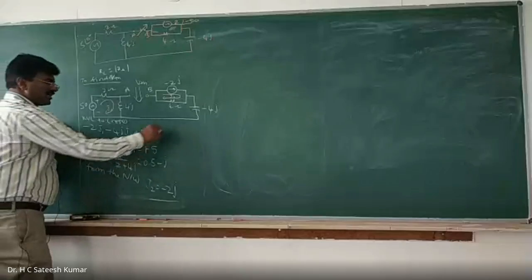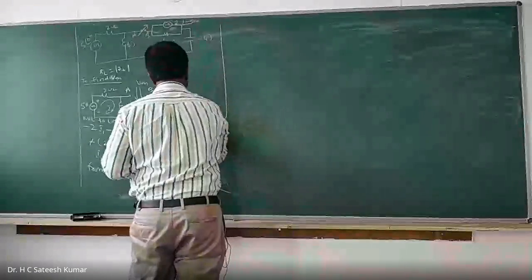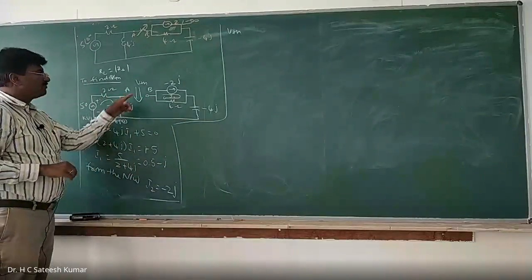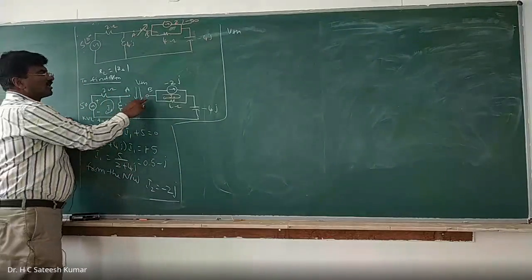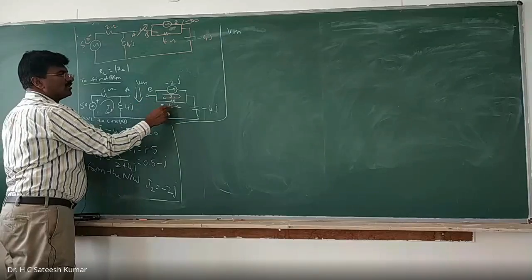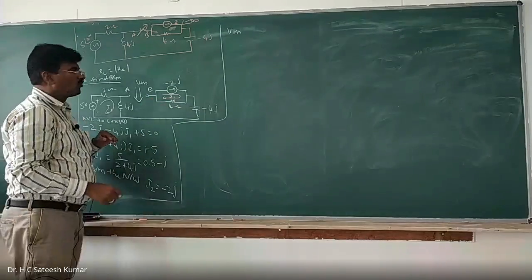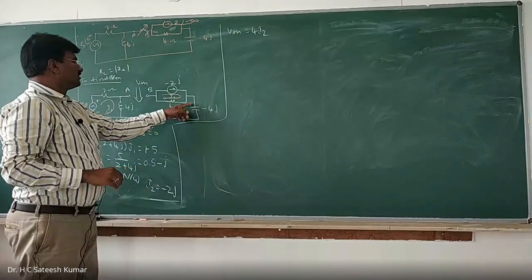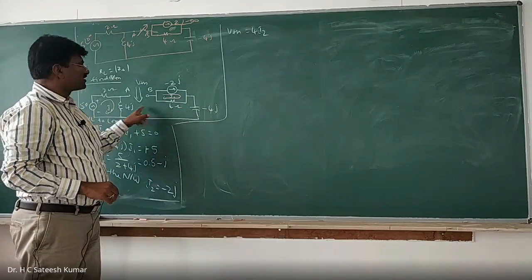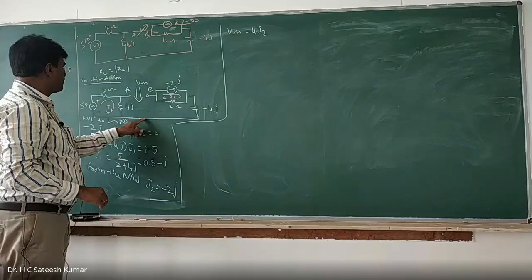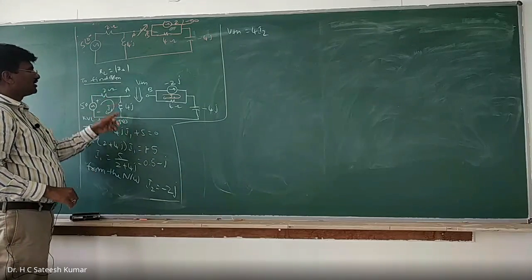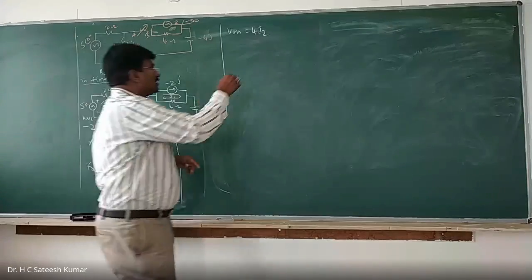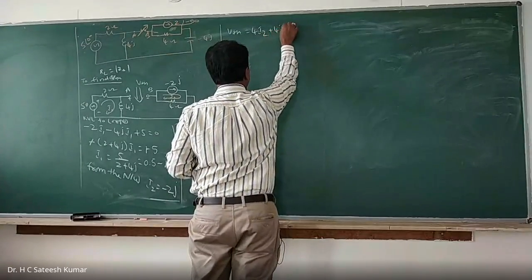Okay, right. Now what should we do? For VTH, you'll have to go from B to A once. I can't go this way, as there is a current source, so I'll go this way. Against the current, plus 4 into I2. VTH is equal to 4 into I2. Next, here current will not flow because it's open circuited, so I'll come back here. I can go this way or this way. Easiest is this one. I'm going against, plus 4j into I1.